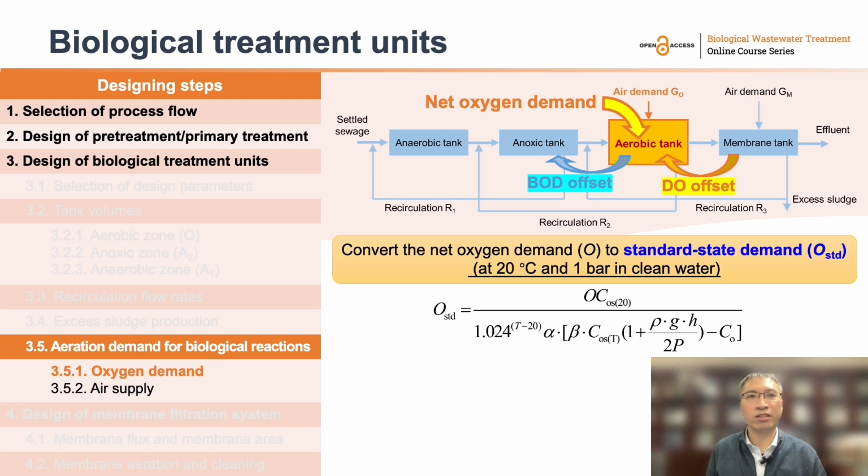Here shows the equation for the standardization of the oxygen demand. This equation is comprised of temperature correction, pressure correction, sludge correction, and DO terms.